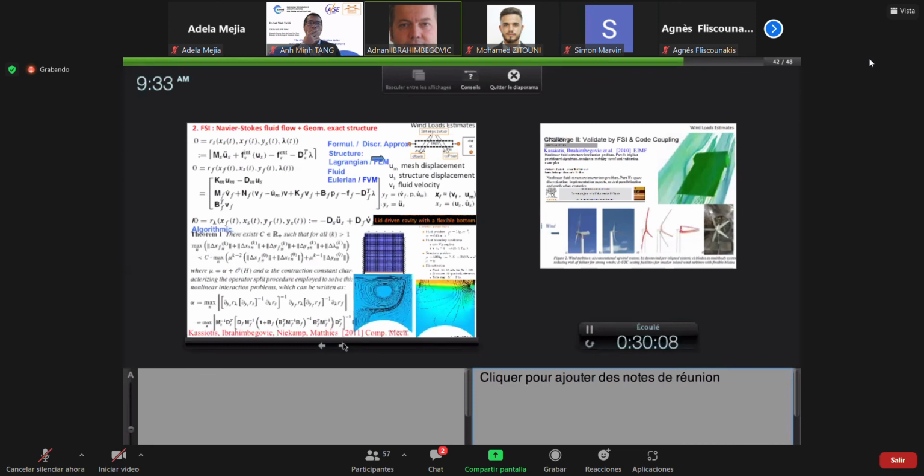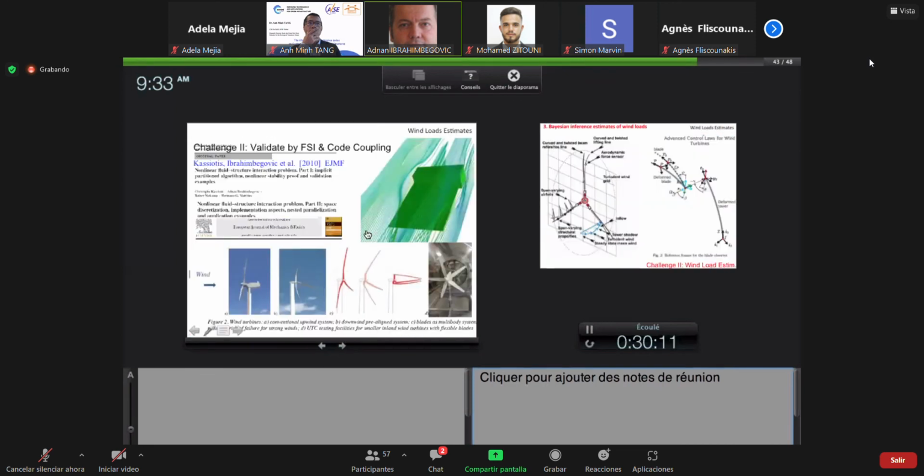Normally, we are not only interested in these benchmark problems, but it's difficult, and I'm sure that we're interested now in modeling something in a turbine. Here, we took a very simple 2D model, and you can see the illustration of the geometrically exact model vibration and the streamlines, and you can see that it becomes much harder to control. Now, what we really plan to do is turn these blades into a multi-body system. And when you reach this ultimate type of loading, you simply release the joint and you let these blades flow like a flag. So you avoid the risk of breaking the installation, which typically is likely to be very costly if you have very strong winds.